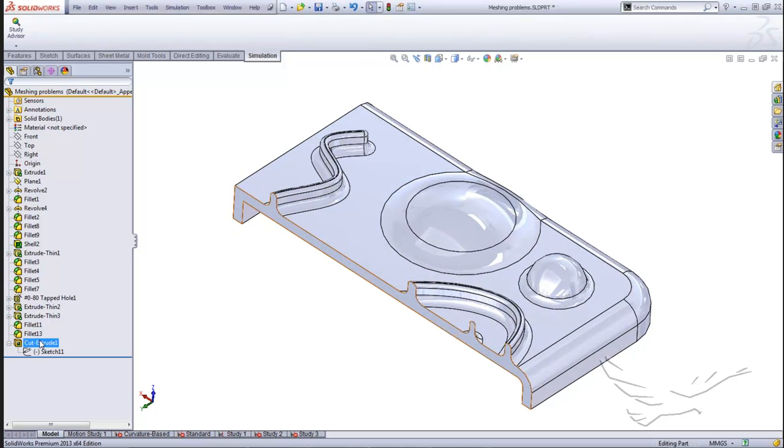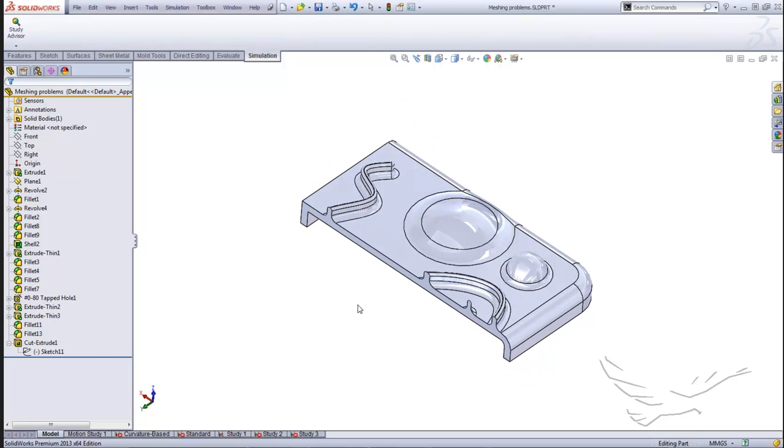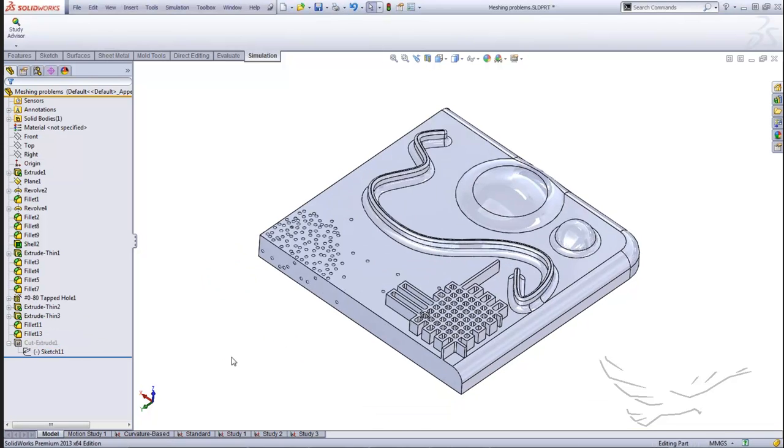And when you find a problematic location, you'll be more easily able to resolve that issue at that location, because you'll also have a smaller model to mesh, so it'll take less time to actually complete the mesh, and so on. So that's an aggressive piecewise approach that you can take at the part level: physically cut the part into a half or a quarter to run along with that.